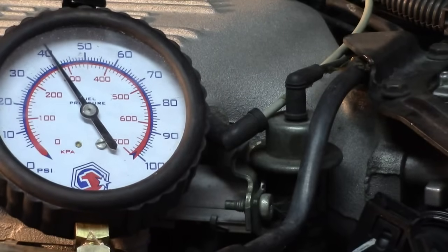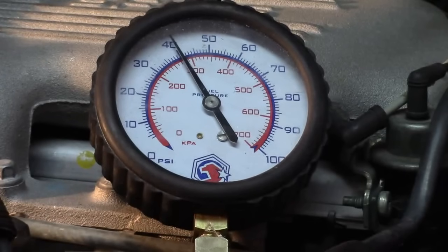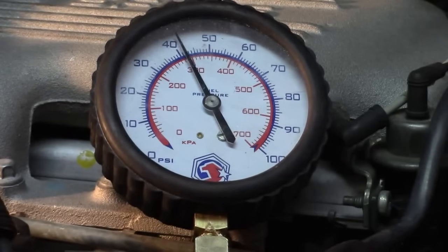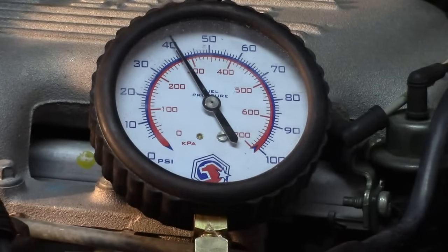Okay, so we've got the car started. We see the fuel pressure actually dropped a little bit to about 40. So one of the first things we want to do, does the fuel pressure drop when we add throttle? And we can see that it does not drop when we add throttle. If we had a P0171 or 0174 lean condition, or 0171 and 0174 on a V engine lean condition, and we saw a good drop, that would be almost certainly why we would have that check engine light code for the lean condition.